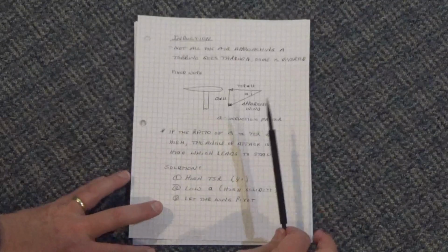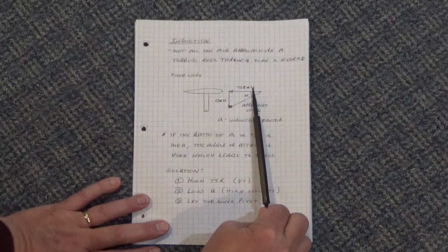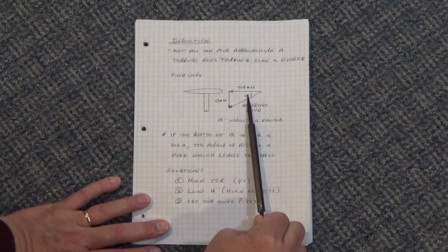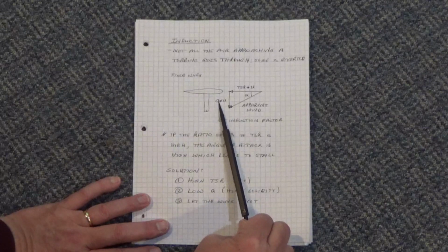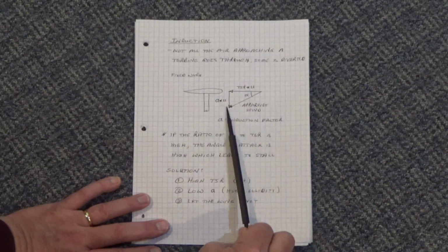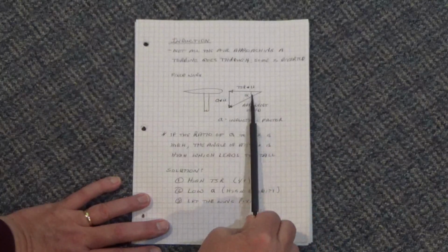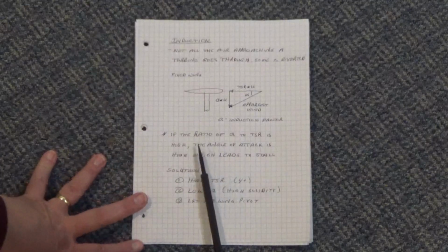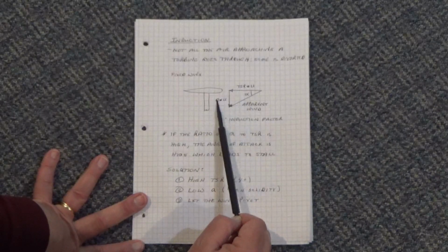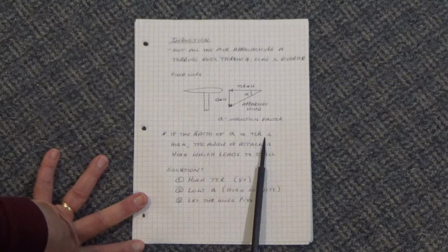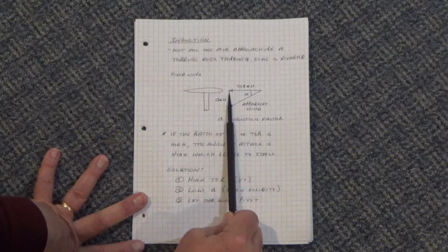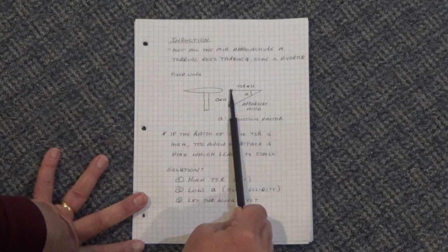So this has a factor of U in it, this has a factor of U in it, so really this angle is defined by this number A, the induction factor, and the tip speed ratio. You can take the inverse tangent if you want to get this angle. So what really matters is this ratio of the induction factor to the tip speed ratio. If this is a big number, that means this is fairly large compared to that.